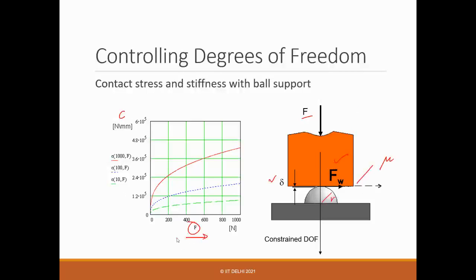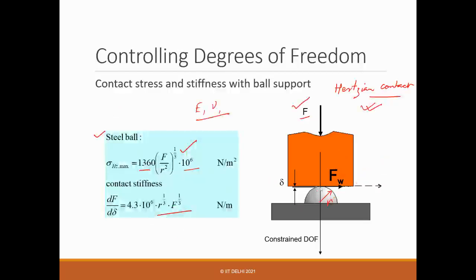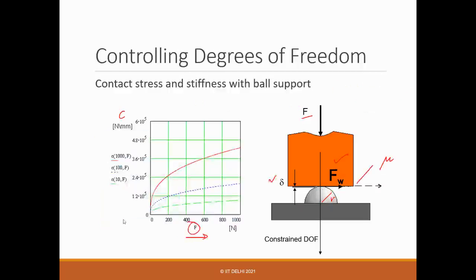One consideration is load capacity. F will basically be the load capacity for a given arrangement, and this will be limited by the stresses. So what stresses will you get? These stresses will be the limitations, and in order to prevent failure, you have to consider them. And this is more about dynamic performance, the stiffness.